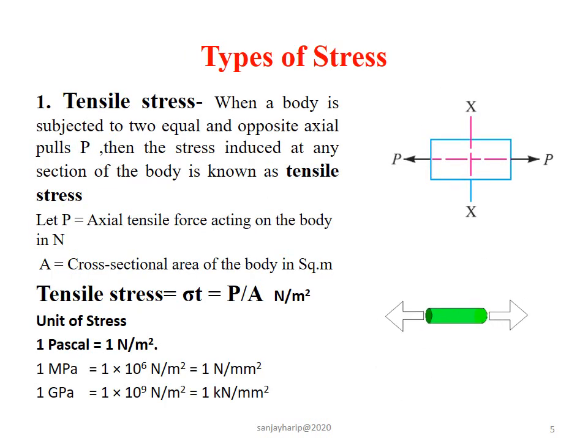Let us revise the term stress. What is stress? When an external load or force acting on the body, the internal forces are set up at various sections of body. These forces resist external forces. These internal forces per unit area at any section of body is known as stress. There are different types of stresses like tensile stress, compressive stress, crushing stress, bearing stress, shear stress.